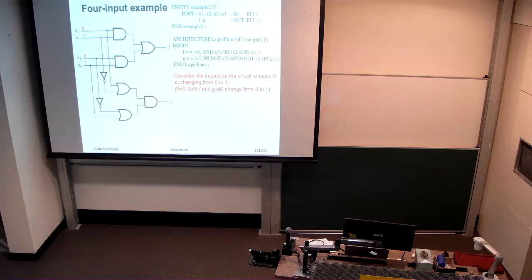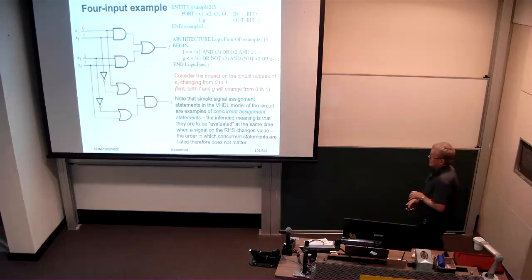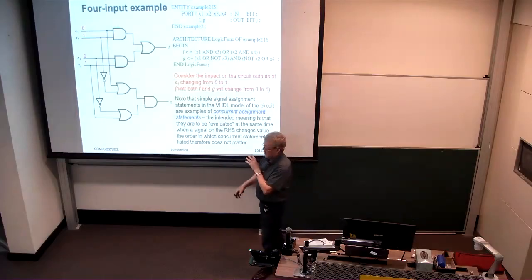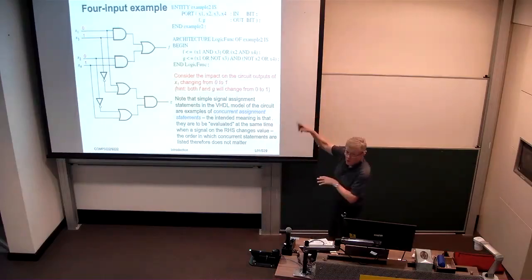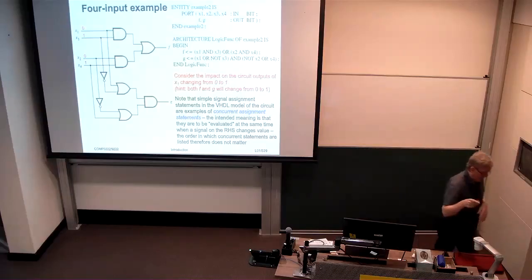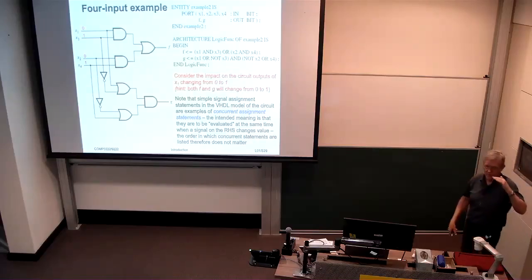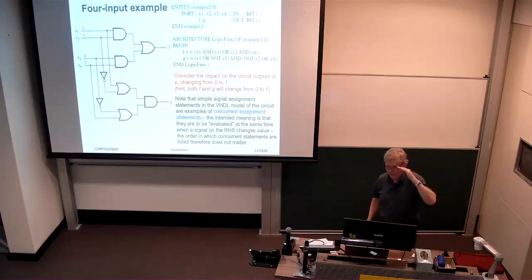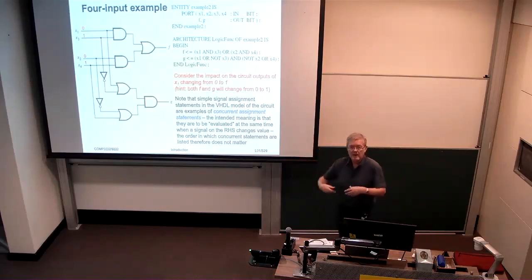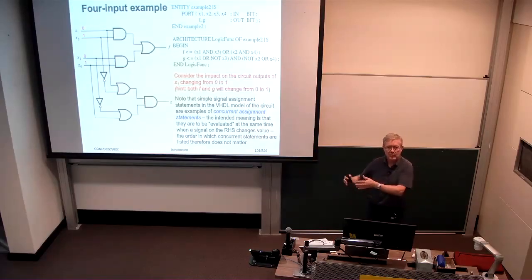Same time, good. Yeah, they're examples of concurrent assignment statements. All assignments are concurrent, so the order in which we list the assignments doesn't matter. This is different to a programming language, where normally the top to bottom sequence of instructions indicates a temporal sequence of how they should be evaluated. You always evaluate the first statement before the second statement, or it should be in terms of its logical sense. But this is a description, and as a description it doesn't matter what order, because we're not describing the order